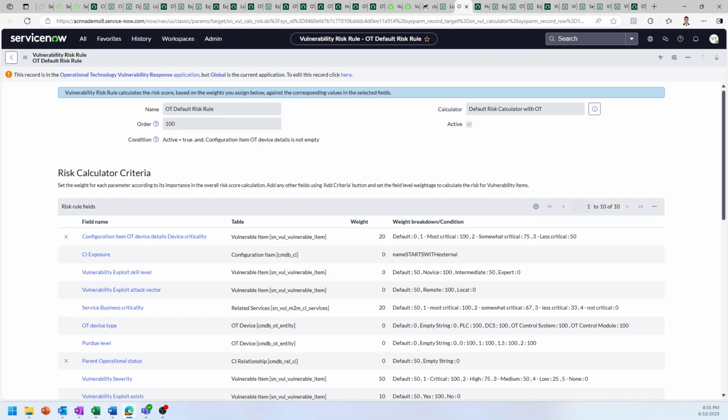Typically, OT asset criticality in IDS would only capture the network related criticality aspects. And this is where we can leverage the criticality of the manufacturing processes to rationalize the risk score. Let's say we have the same vulnerability across two PLCs with a similar network configuration, but one of them is in a critical process area. We may want to have a higher score for this PLC's vulnerability. This is the interface that allows us to configure that logic.